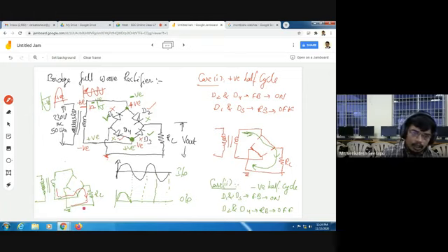So here also current flows through the load resistance in the same direction as the current flows in the load resistance in case of a positive half cycle. So here also I am getting a positive half cycle as an output only, a positive polarity as an output. Why? Because whenever I am applying a positive half cycle, the current flows through the load resistance in this direction, up to down.